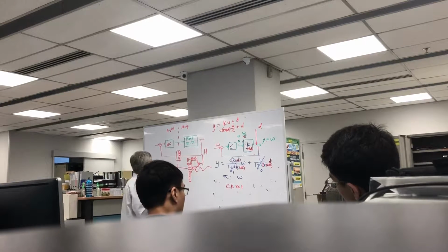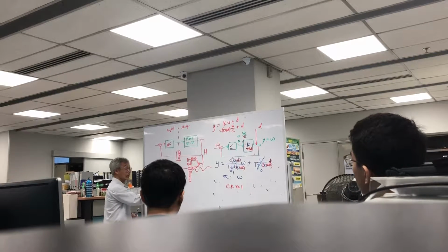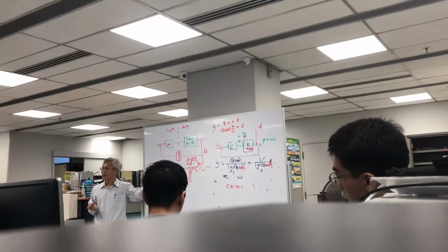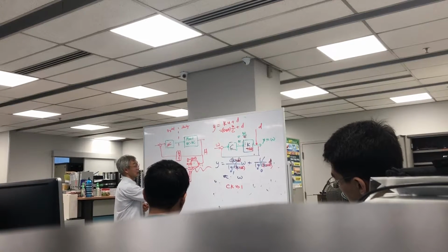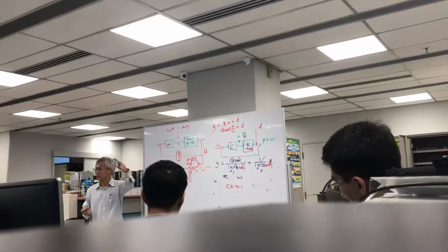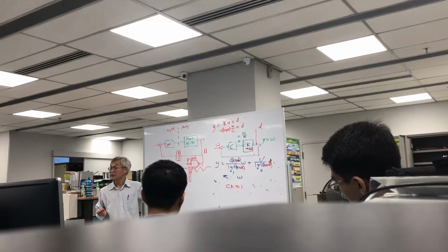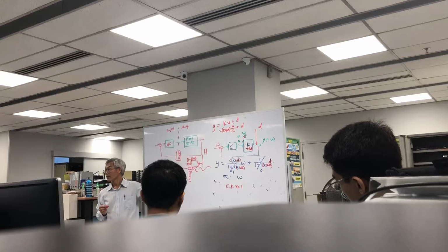An encoder is some disc that you shine light through. How does the encoder measure speed? Pulses, right? You count the number of pulses per unit time, then you can deduce the speed. Then what kind of interface do you need? You need some digital input, which is like an up-down counter. So these are the key components.